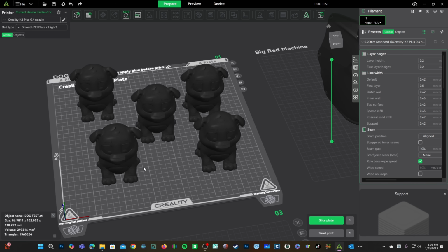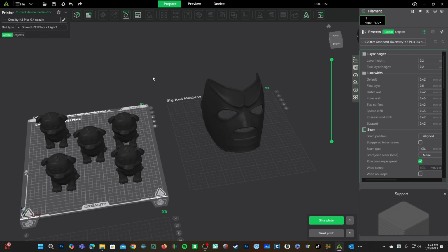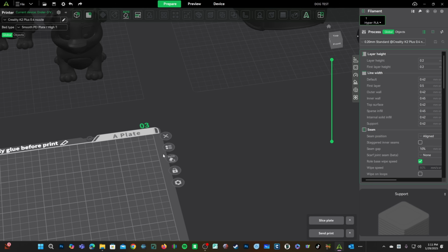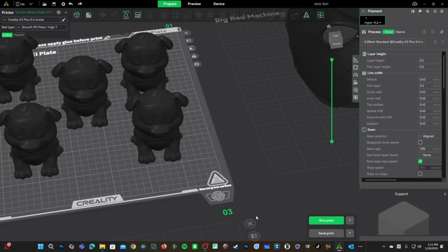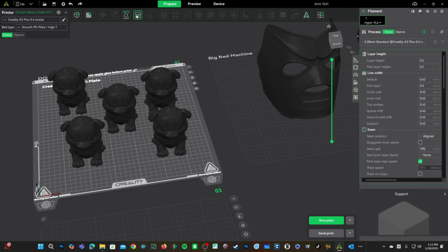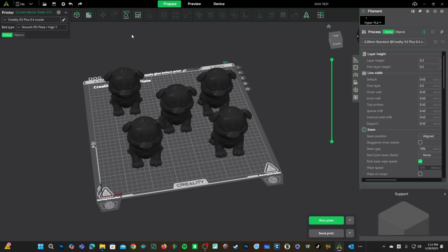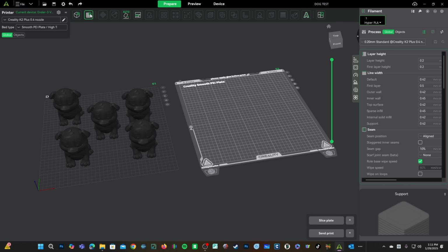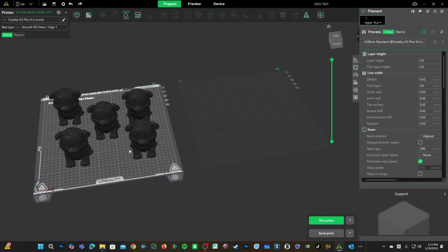This brings us to the Arrange tool. There are 2 different Arrange tools. One is here on each individual bed. That Arrange tool will affect only its bed. There is then a Global Arrange tool, which will arrange the entire project. If you have only one bed, this Arrange tool will affect only this bed. However, if you have multiple beds, the Arrange tool will attempt to arrange all models on all beds, and this may include attempting to stuff them all into the same bed.